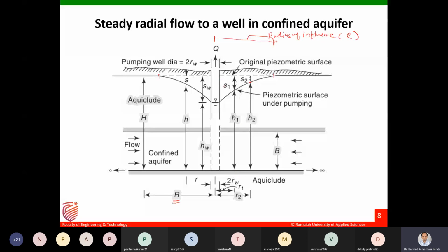Normally when you are measuring the groundwater, we measure from the top. We are not sure of what these levels are, and they are difficult to estimate. If we know the total depth of the saturated zone, what we can measure from the top is the S1 and S2 values, which are mentioned here. Those S values are nothing but my drawdown, and this you can calculate.